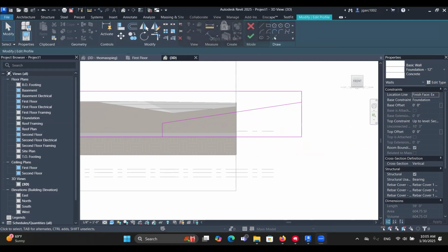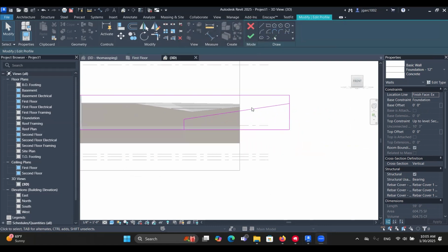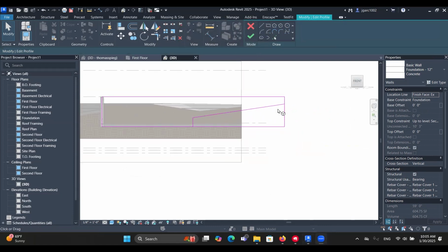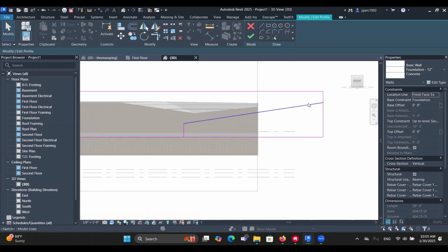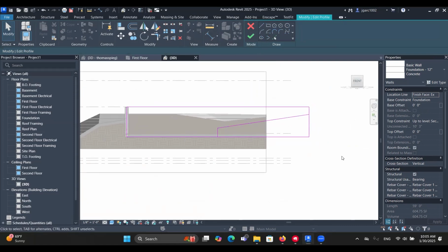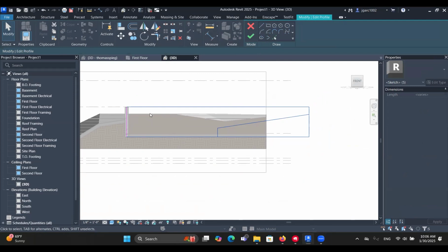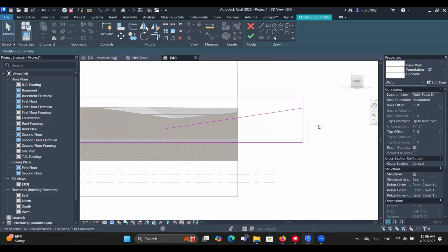This is another one that you guys may use. So TR equals trim. And trim has a funny way of working here, because trim doesn't work how it usually works in other software, where you have to select the lines that you want to trim. Trim here works without selecting. So basically trim is going to prompt you where you want the lines to meet.